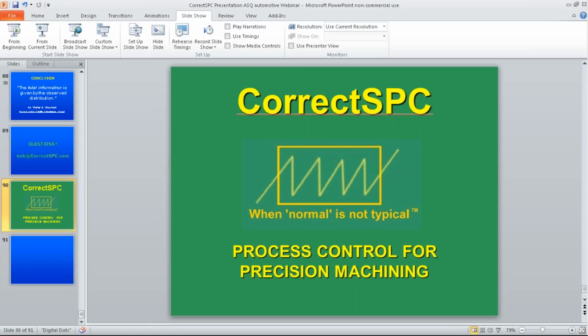But this particular index is simply trying to find out where your distribution fits in the specification. It just so happens your distribution is, by design, your upper control limit minus your lower control limit. And if it's 75%, then it's 1.33. If it's 50%, then it ends up being 2 or whatever. But the problem is, if you compress your control limits to get a higher capability, then you have more operator intervention, more adjustments with very little economic benefit to you or your customer.